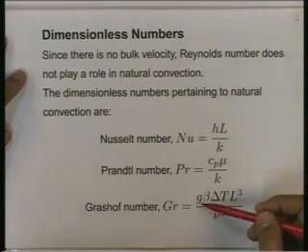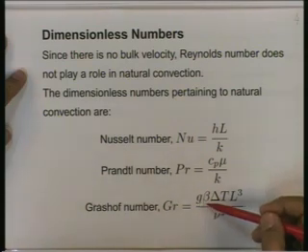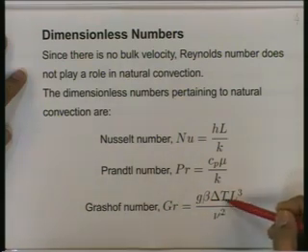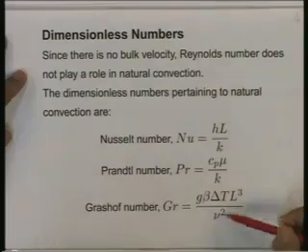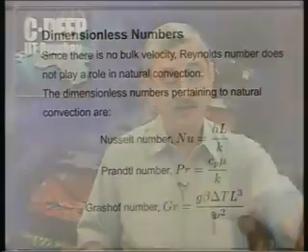It has the gravitational acceleration, coefficient of expansion, temperature difference, length and viscosity. Let us look at the Grashof number, its significance and how it comes about.